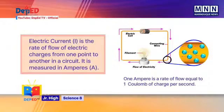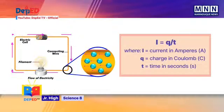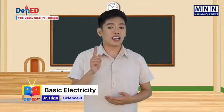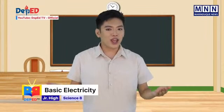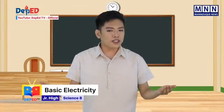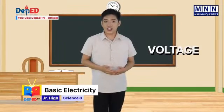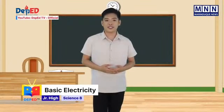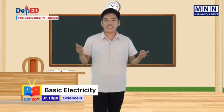Mathematically, electric current is given by I equals Q divided by T, where I stands for the current in amperes, Q, charge in coulombs, and T, time in seconds. A sustained current in conducting wire requires a suitable pumping device, meaning charges will flow only when they are pushed or driven. The work needed per unit charge to move between 2 points is called voltage, expressed in volts. Voltage is what makes an electric charge move. It is a difference in electrical potential energy per unit of charge between 2 points. Simply put, it behaves like a pushing force, forcing electrons to start moving around, which creates an electric current.